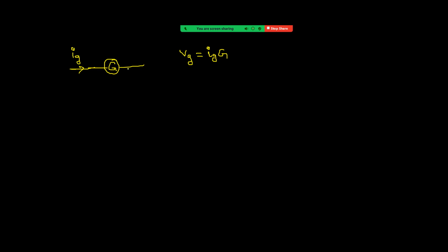Now, if we connect a high resistance, take it as R, this entire arrangement we call a voltmeter. See what we are doing here. We are increasing the resistance. When resistance is increased without changing current, we can increase the potential difference.